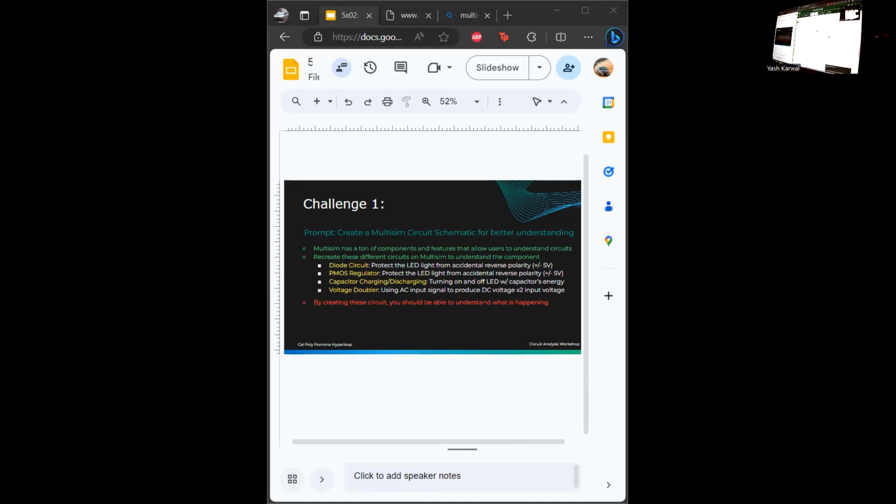So what's the rule of thumb when we have an LED? A resistor. You don't want to kill that LED, and you don't want to blow it up like Chris did with his capacitor. So we have a resistor. We can keep it at 1K.